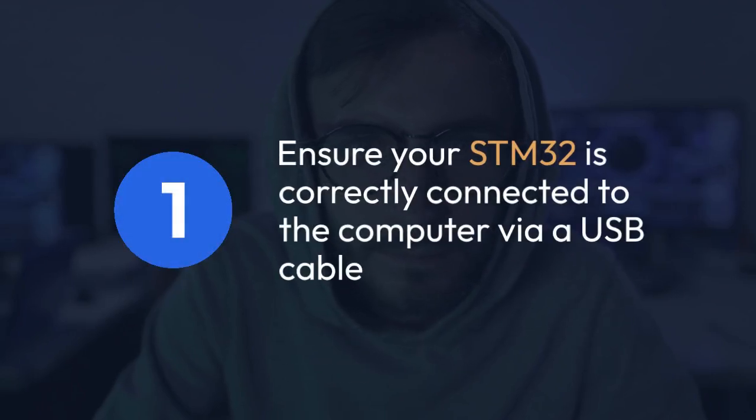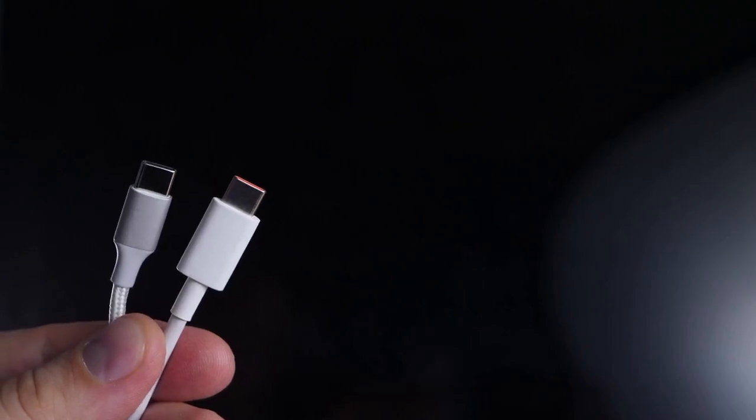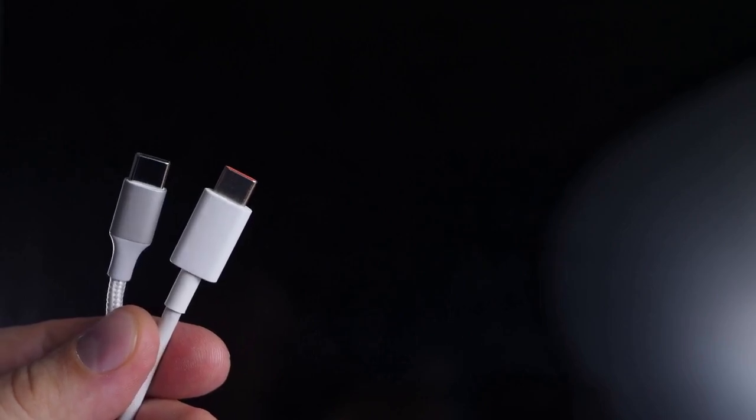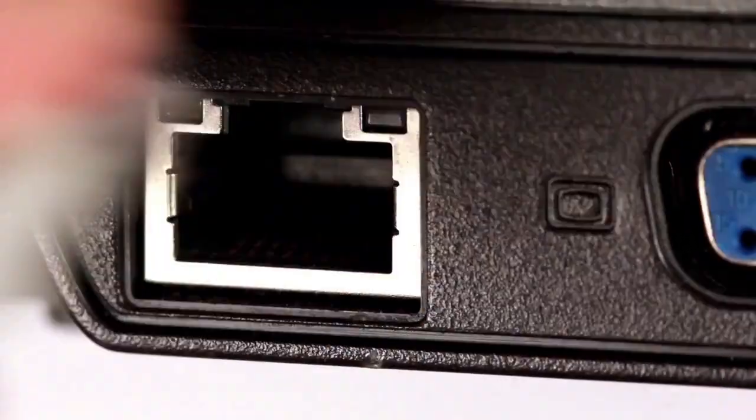1. First, ensure your STM32 is correctly connected to the computer via a USB cable. Check both ends. Make sure the cable is securely plugged into both the STM32 board and your computer's USB port. Try different USB ports on your computer. Sometimes a port might be malfunctioning or not supplying enough power.